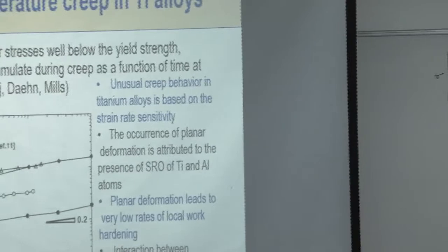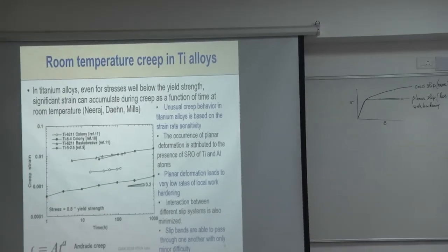I'm going to show you Neeraj's results actually, that the interaction between the slip systems is also minimized, okay? So the slip bands are able to pass. Let me show you, then it'll be much easier to explain.